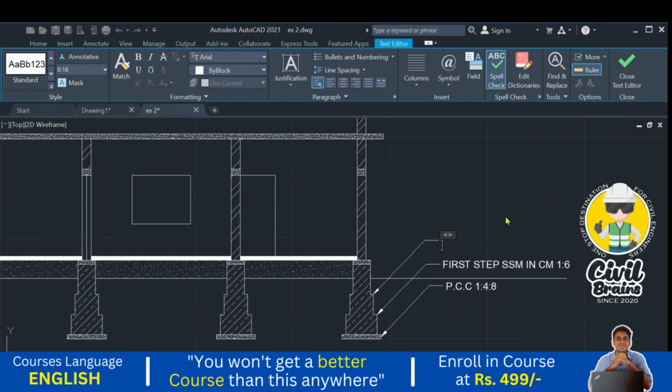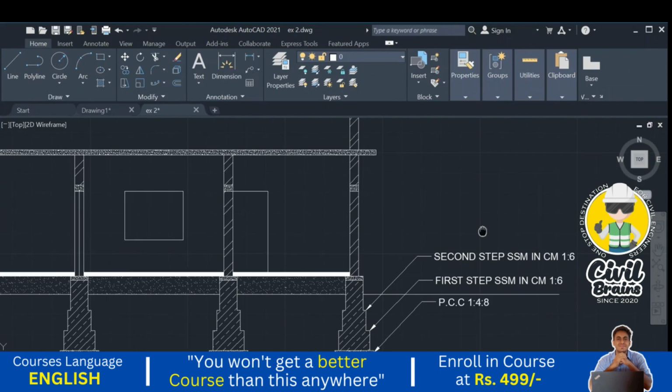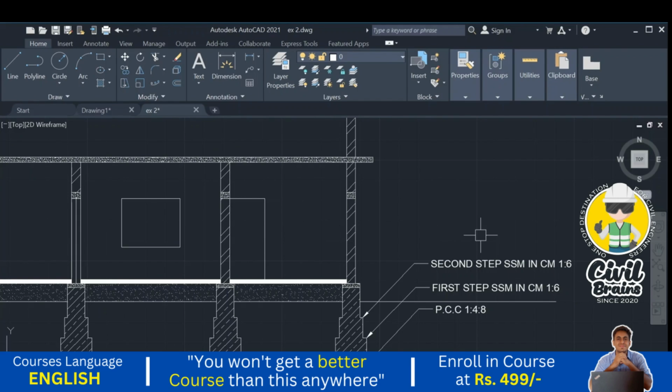Next, second step, SSM in CM, 1:6. So for the stone masonry and for the brick masonry, or for the masonry work, we are taking the cement mortar of ratio 1:6. 1:6 in the sense 1 part is cement and 6 parts is the sand.